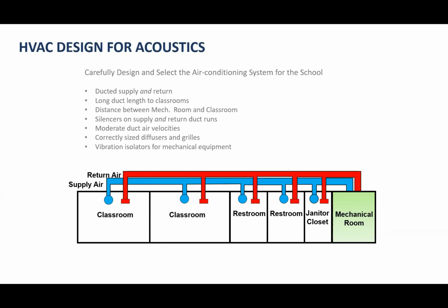But the background sound level of a classroom, so that you don't have to have additional vocal effort and strain on the teachers, is probably going to want to be around NC 30 to 35 dBA. And we're going to see some of that again in some criteria a little bit later as well. So if that's the background sound level, then 15 or 20 decibels above that for the source is much more easily achievable without additional effort.